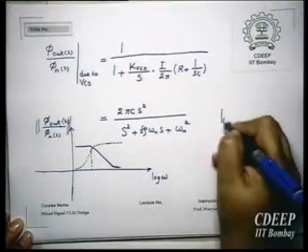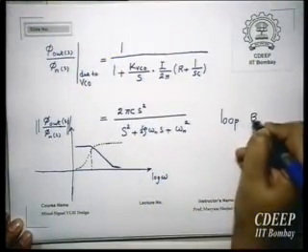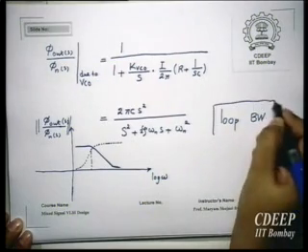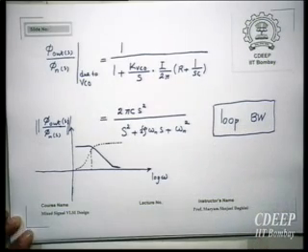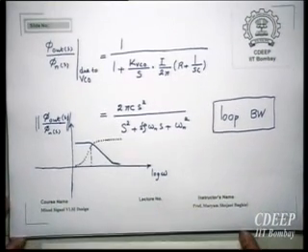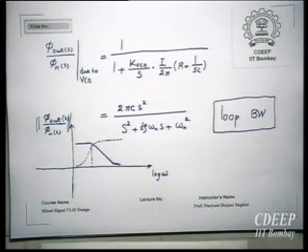There will be other problems also. So loop bandwidth should be optimized. Essentially, after all, the whole point in the design of a PLL is loop bandwidth. It should be optimized very well. And there is one more point here. This is not only a matter of this.